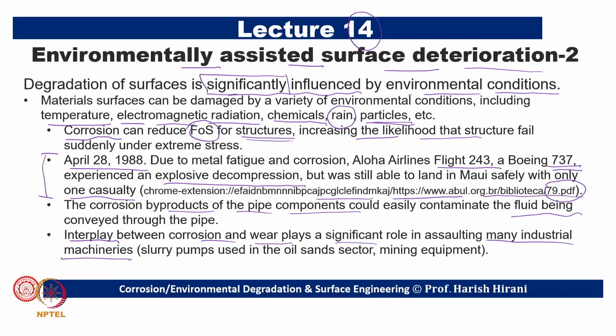We can name a number, but one very common example which I have observed myself is a slurry pump, where a number of particles are present and the pump's erosion happens, and because of that erosion, new sites and new material are exposed to corrosion, and it deteriorates at a faster pace.